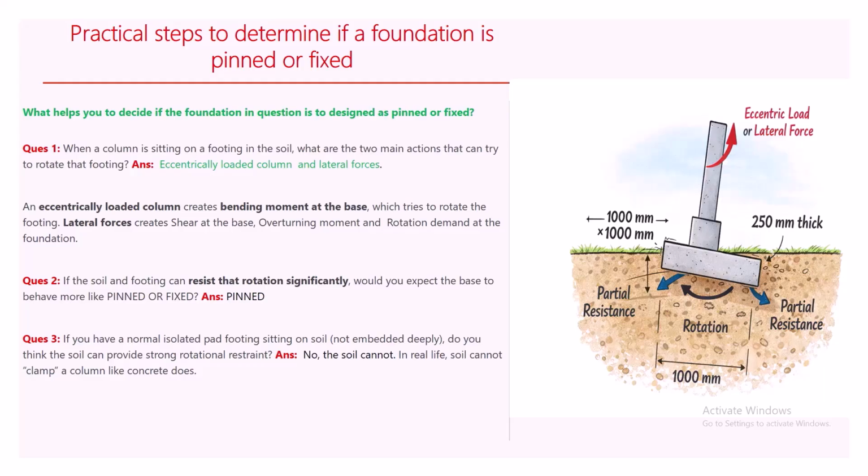Okay, so if you have a normal isolated footing sitting on soil, not embedded deeply, do you think the soil can provide strong restraint? What you have to know is that it is not embedded deeply. If it's not embedded deeply, the soil cannot provide strong restriction or resist rotation.